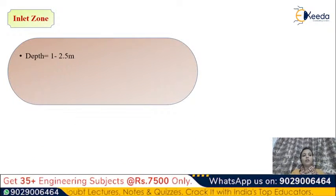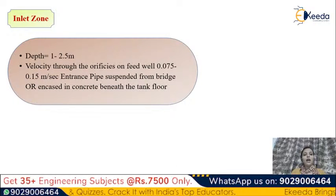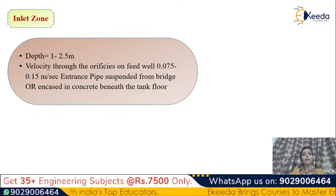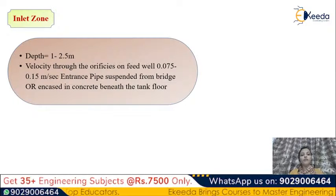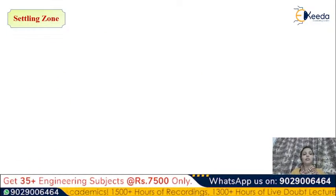The depth of a circular sedimentation tank maintained should be 1 to 2.5 meter, and the velocity through the orifices on the feed well should be maintained at 0.075 to 0.15 meter per second. The entrance pipe is suspended from the bridge or encased in concrete beneath the tank floor. So these are some of the design criteria or parameters we are following during the design of a sedimentation basin.